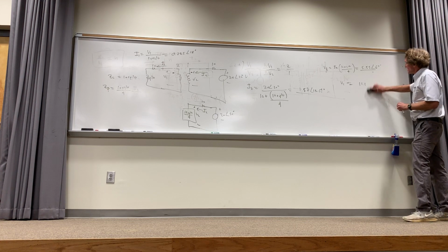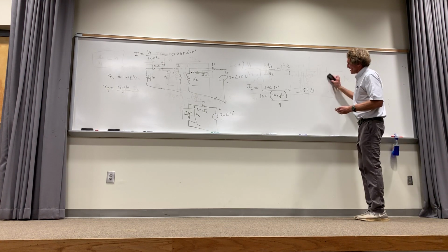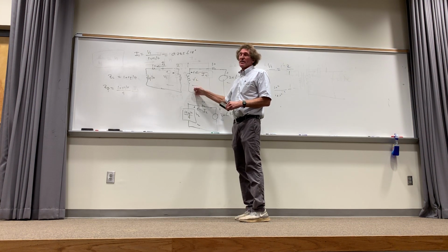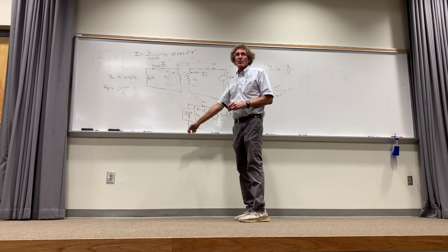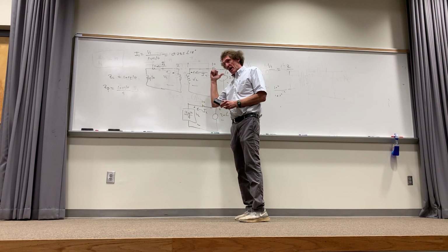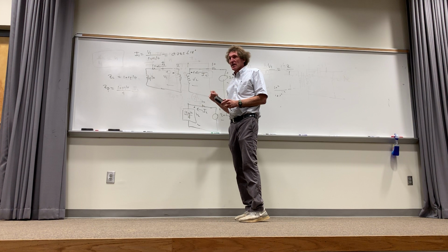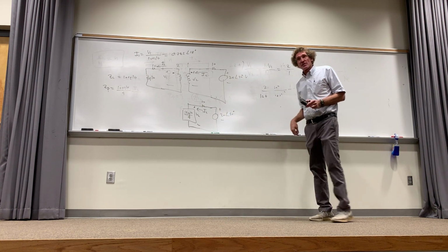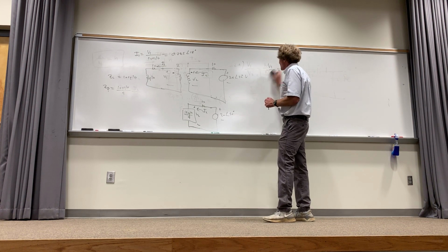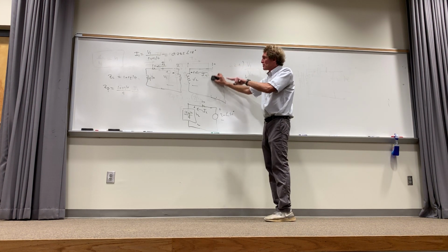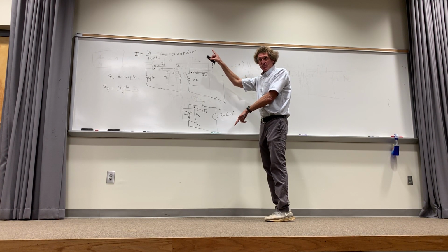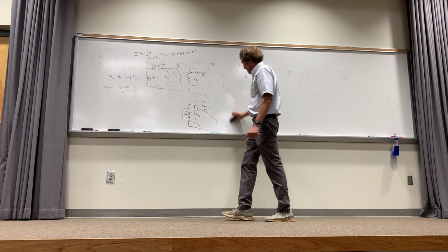Now, real transformers, I want to tell you, they won't have just one secondary. There'll be 3 or 4 coils off the secondary where they're pulling things, and the sum of the power going out is equal to the power coming in. Those are more involved. That's an electrical engineering problem, not for people that aren't electrical engineers. But you should be aware that in the real world, if you see several actual windings in the secondary with voltages, that's very common.